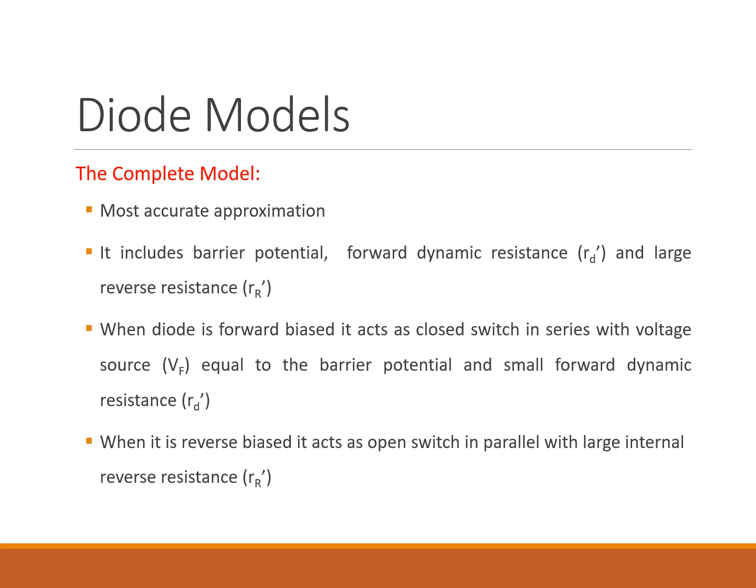So the resistance R sub E prime times the forward current gives us the total forward bias voltage. And reverse bias is equal to that large R sub R prime. It ends up blocking current, but again, reality has a tiny leakage that goes through. These are best used when you're working with detailed, precision types of analysis, right?